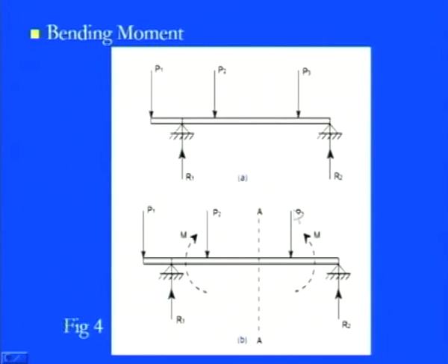So if you go for the overall impact, then you will find that we have a bending moment which is going in an upward direction, and the tendency can be easily shown by this dotted line, and we have a magnitude M of these things. So you see here, we have a bending moment which is going in this direction. So, this direction is there. It means that the overall impact of these forces on a beam will give you the overall bending moment in this particular cross section.